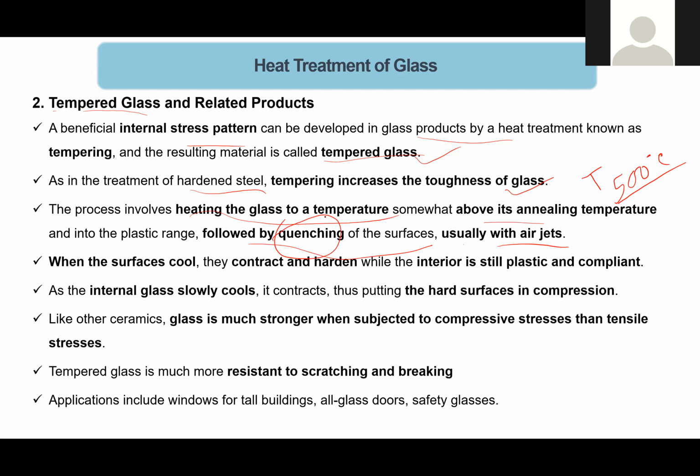Yes, of course it can make it brittle, it depends on what temperature you are working on. For example, if we consider a metal like steel, you raise the temperature to produce the austenite, then keep it in the austenitic state for some time, and then rapidly quench it to allow the reorganization of the material. The same thing actually happens here.